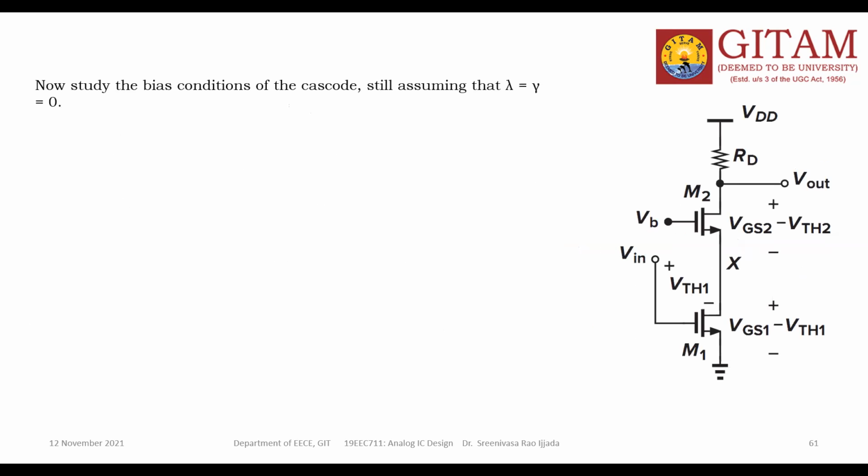Yes, Vx value. For the first transistor to be in saturation, Vx should be greater than or equal to VGS1 minus VTH1. Similarly,